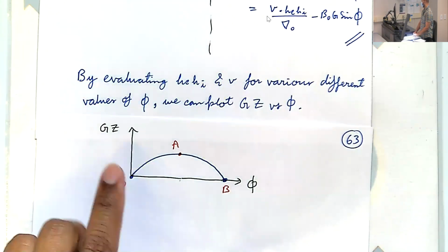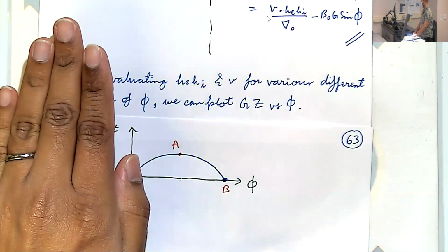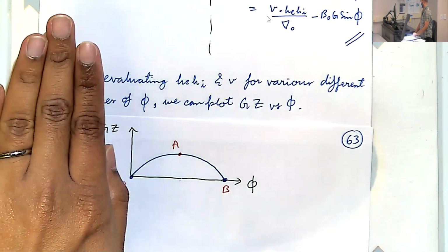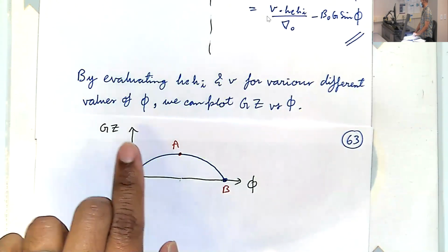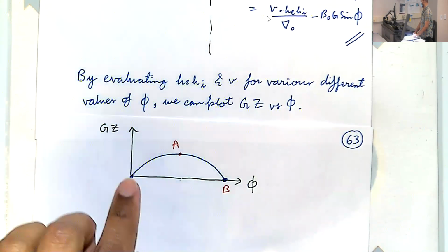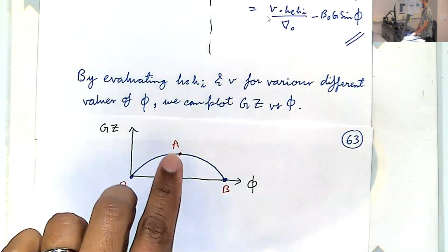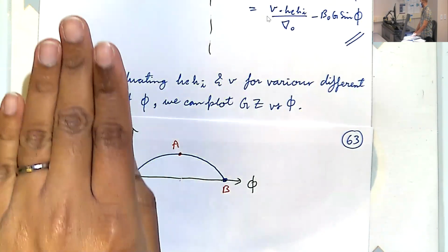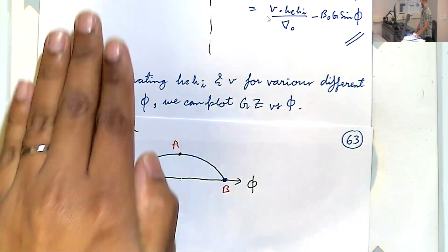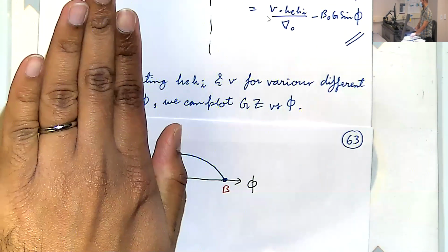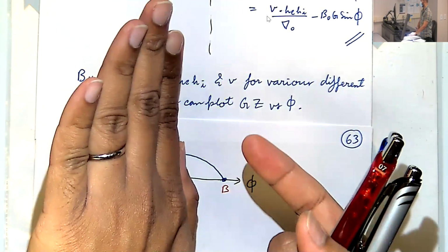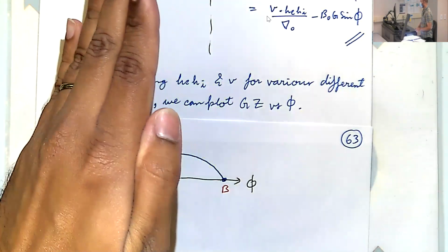And if we start increasing the angle slowly, the restoring torque starts increasing. Okay, and it'll keep increasing up until some point. So when you heel your ship to, let's say this is 25 degrees, that's the moment when your ship really wants to bounce back. Okay, you have a lot of torque trying to restore its state.